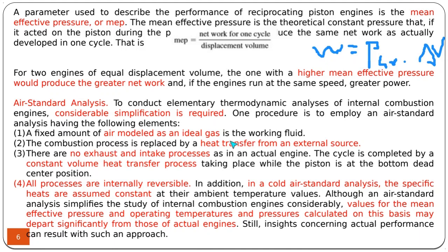Combustion process is replaced by a heat transfer from an external source. So we assume the system to be a closed system, which is normally not, because when the inlet valves and exhaust valves are open and closed, there is actually mass coming inside and leaving the system, which means that it's actually an open system, but for analysis purposes, we assume the system to be a closed system,